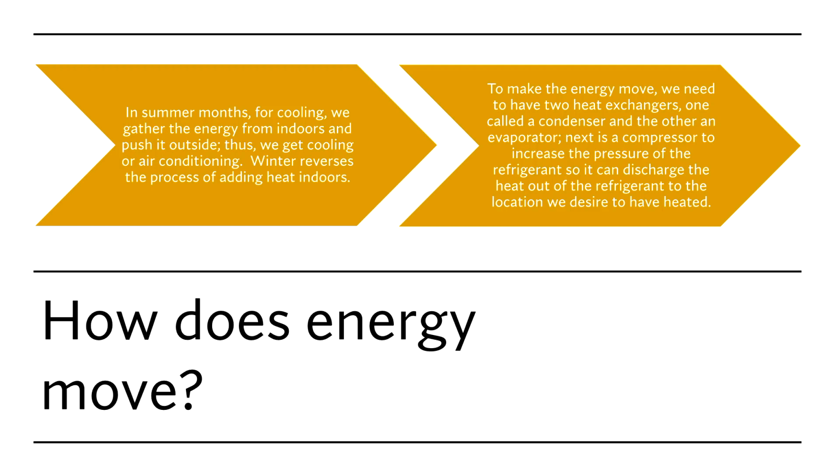Okay. We also need a compressor. I said that the rules of thermodynamics and how we get refrigerants to boil is the heart of the thermodynamics. Well, the compressor is actually the physical heart of a refrigeration system. It needs to take in a vapor and it squeezes it into smaller packets of refrigerant and adds heat to it and raises it in temperature and sends it to the condenser unit, and the condenser rejects it.